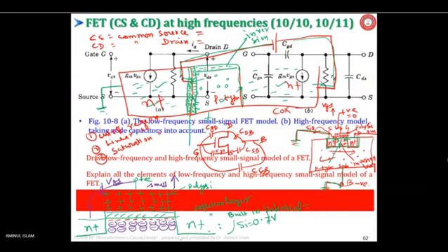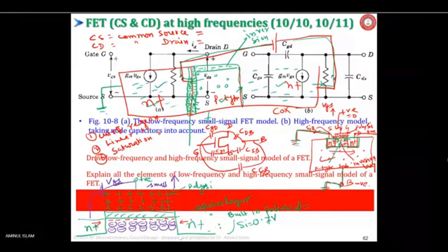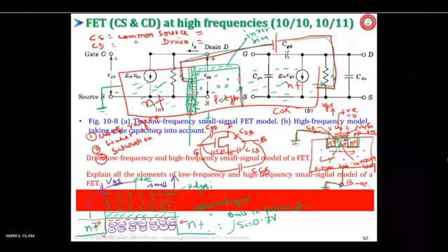My question is, where are these electrons coming from? We discussed that they cannot come from this side. They also cannot come from this side because on the right side the junction is reverse biased. On the left side the junction is unbiased, because both the N plus and the P substrate are connected to the negative terminal of the battery. There is no potential difference between them. Then my question still exists: how are these electrons lined up there? Is my question clear?